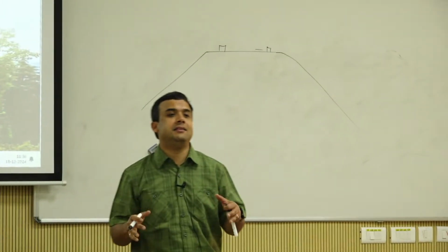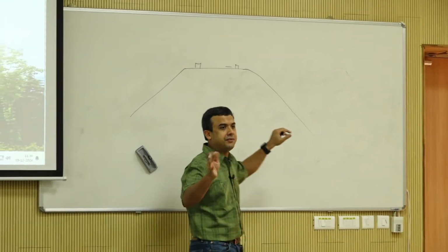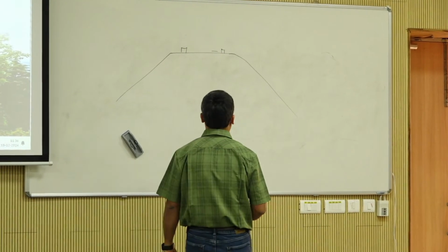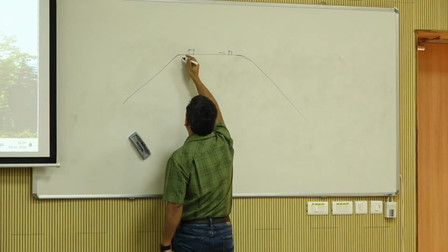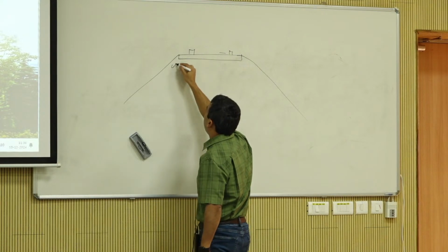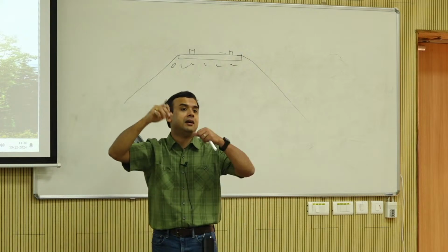When it rains, and this is all ballast, they have a shoulder, and they have certain specifications on how to do shoulders. I'm sure Indian specifications have that as well. The problem is when you have your cross ties here, this is a tie, and then you have ballast all over here, and it starts getting fouled.